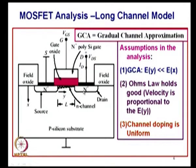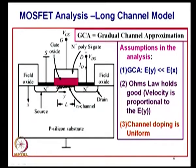Then also you assume that Ohm's law holds good. When you say Ohm's law holds good, what is the meaning? Immediately you say V is equal to I into R. When you say V is equal to I into R, what you assume is that the velocity of electrons or carriers is proportional to the electric field. Okay. That is the meaning of Ohm's law holds good. So, if I know the mobility and the electric field, I can straight away say the velocity is equal to mobility into electric field. Velocity is proportional to electric field, that is Ohm's law.